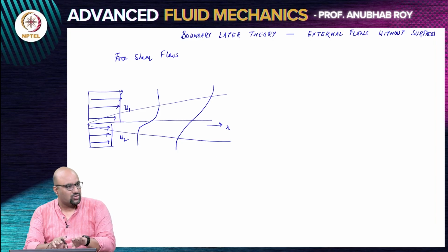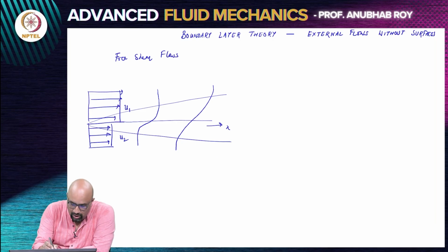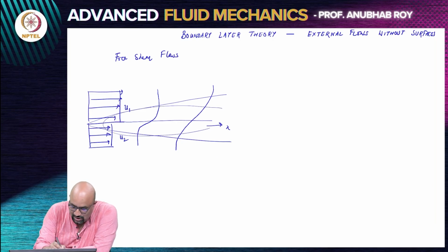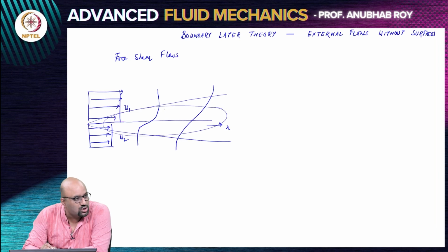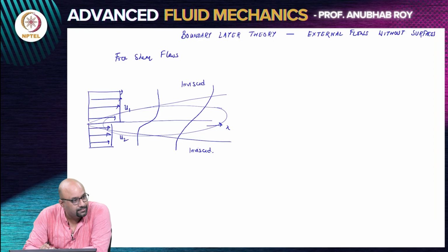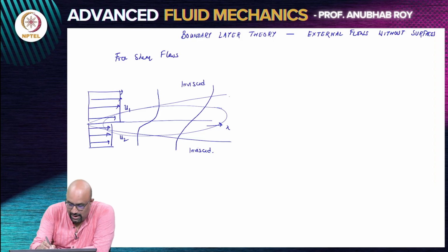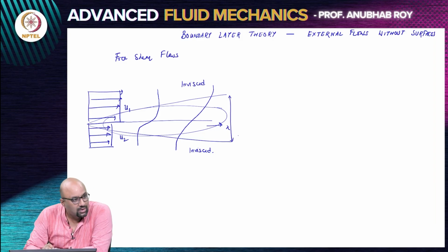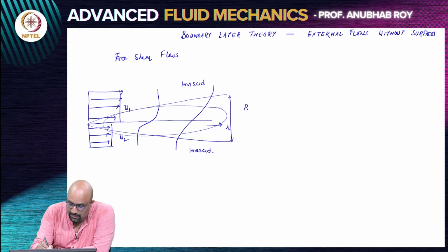So the stream had to come to a state of rest on the surface. Now, there are two streams which are trying to shear past each other. So what you will have is that far away from the interface, the problem is almost entirely inviscid. But in the region which is close to the interface, you will apply Prandtl's boundary layer equations.